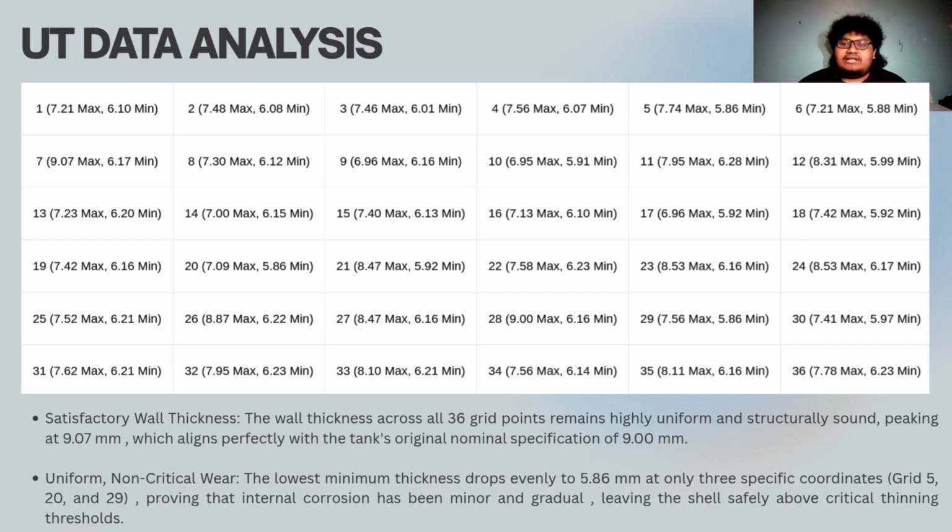Looking at our final analysis, the data confirms a high level of structural integrity. Across the 36-point grid, our peak thickness reached 9.07 millimeters, which aligned perfectly with the tank's original 9 millimeters nominal specifications.